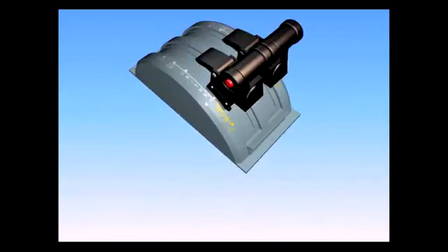The primary controls for the autothrottle system are the thrust levers. In the A320 family, the autothrottle system does not move the thrust levers while adjusting thrust. Normally, after takeoff, the thrust levers are placed in the climb detent, and they remain there until retarded for landing.